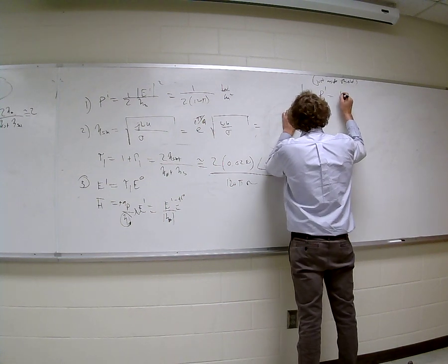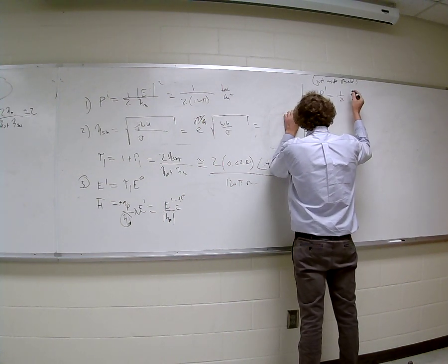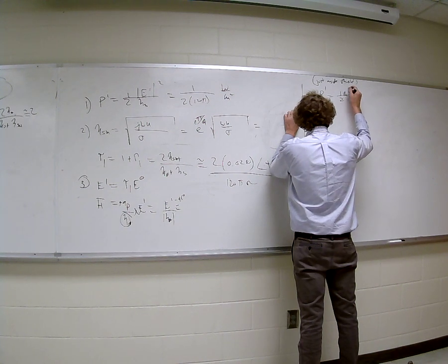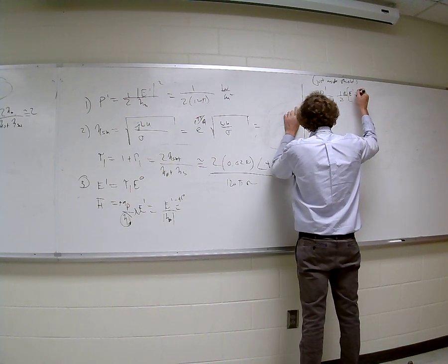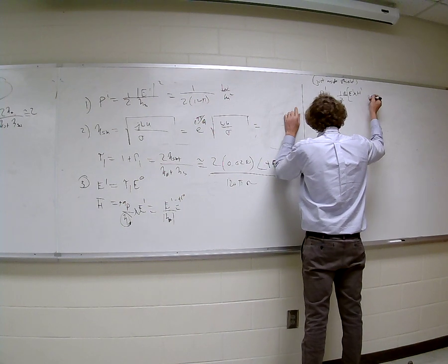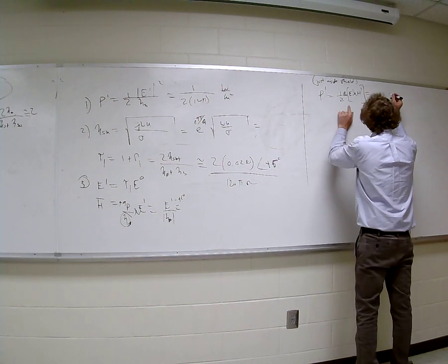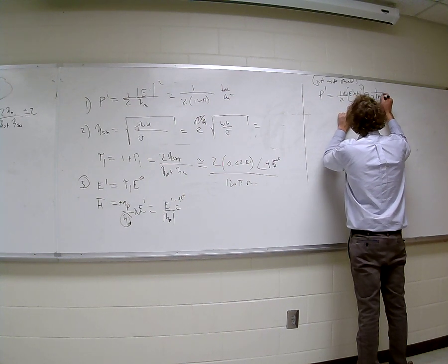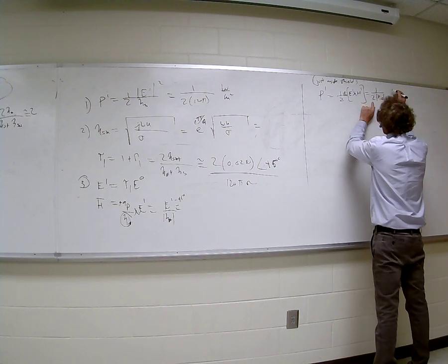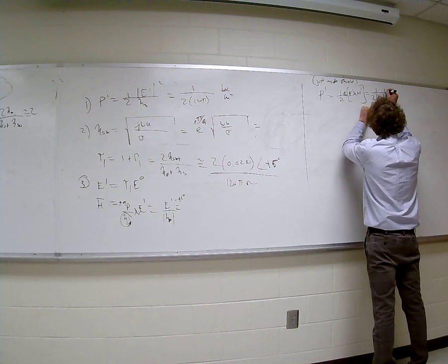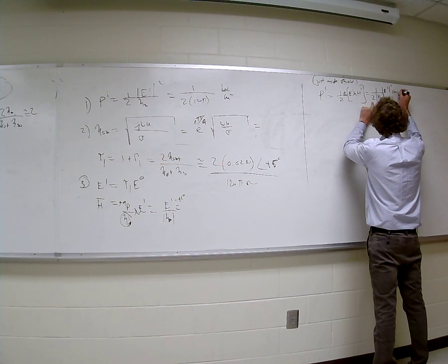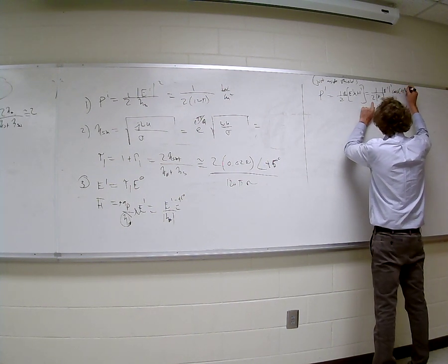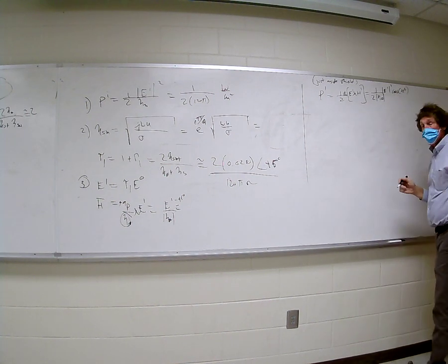Well, that's going to be 1/2, right? And then technically it's the real part. I'll just write this down for completeness. But really, if you look in your book, some people had this right. It's 1/2 the magnitude of eta shield, right? And then it's going to be times the E field prime magnitude squared, times the cosine of 45 degrees, because that's the angle of eta.